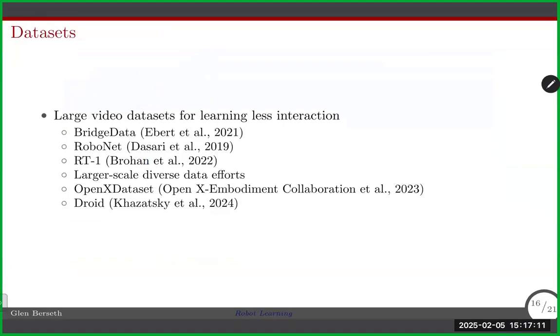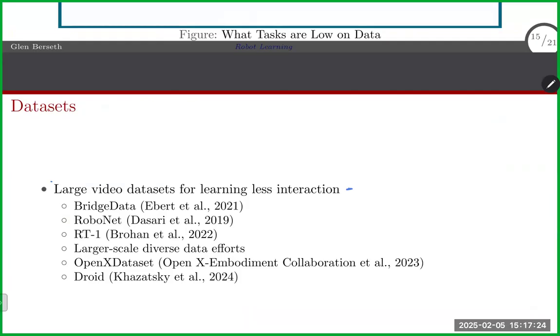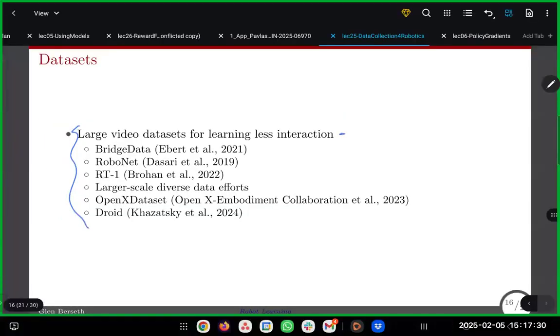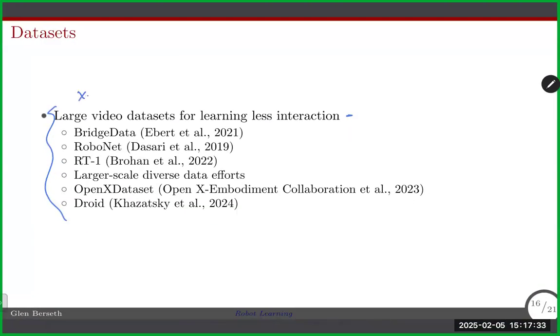Okay. So if you wanted to take that last route, and look at being able to train some models directly from video data, there is a good handful of datasets these days. These are basically all the ones that can be used for behavior cloning because they have X to Y, or what we tend to think of as state to action data. So these are all datasets that have big piles of images labeled with the action the robot took at that particular image. So these could be used to do behavior cloning, some sort of policy training.